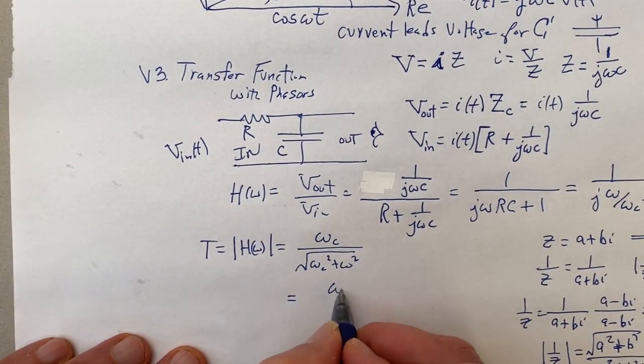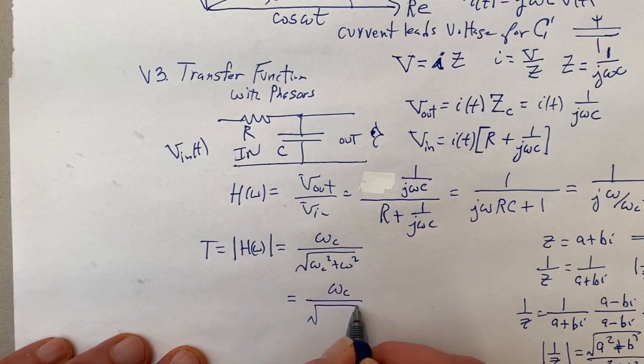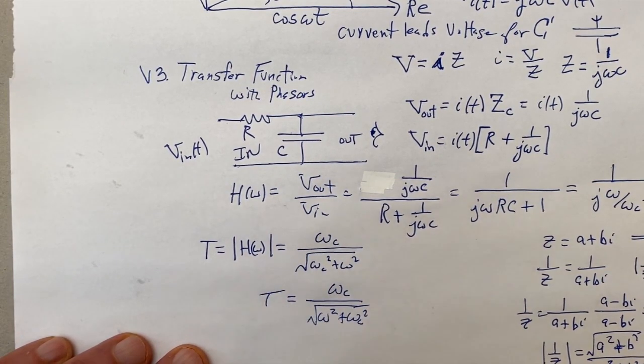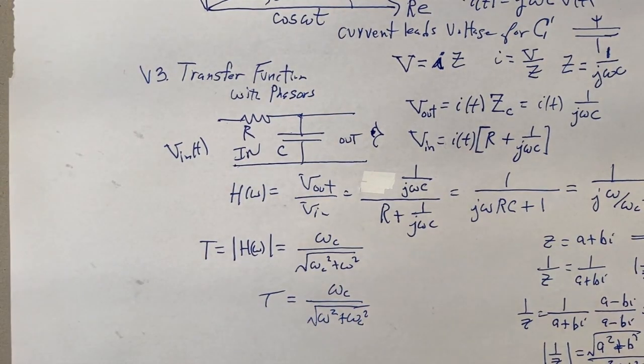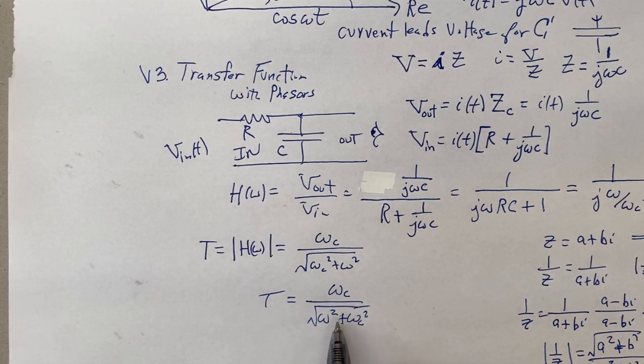And as I like to write the variable first, I'll rewrite that like this. And we have it. You have the transmission function in just a few lines, the transmission for the low-pass filter. So when omega is small, you get 1, or close to 1. And if omega is large, you get 0, or close to 0. So that's very nice, very nice.